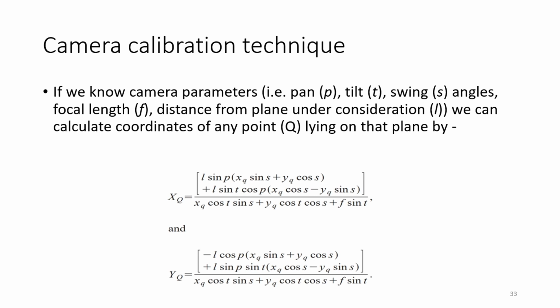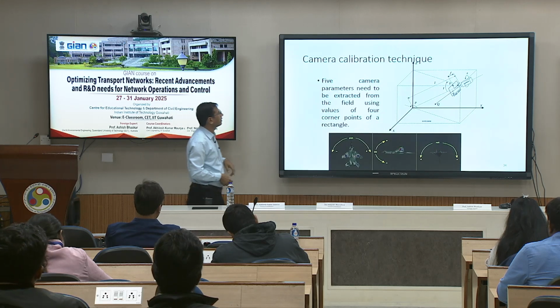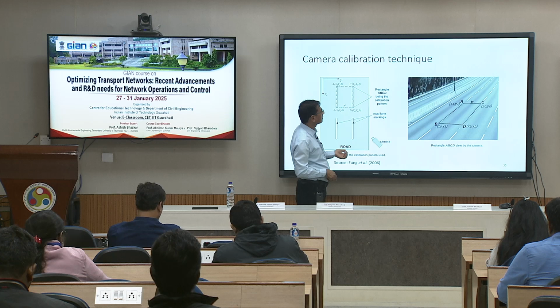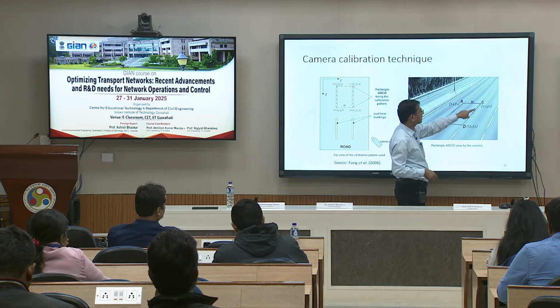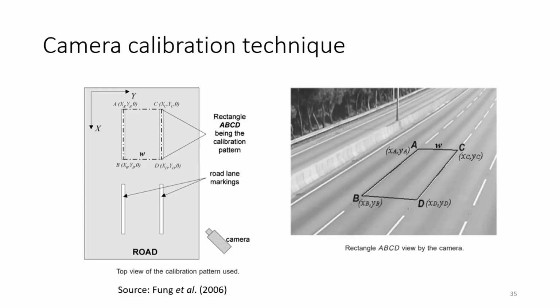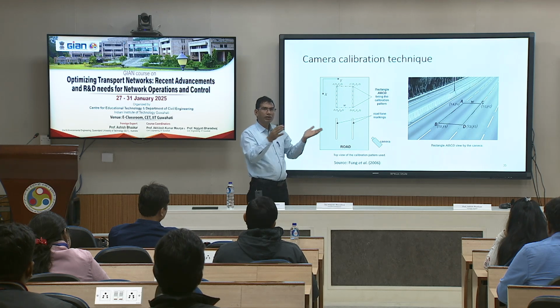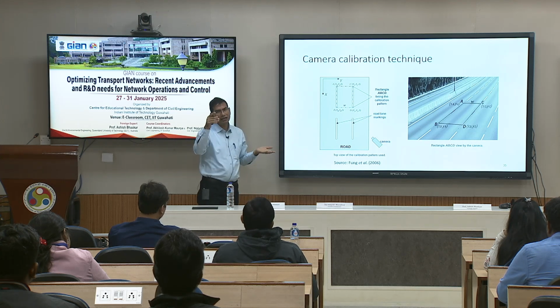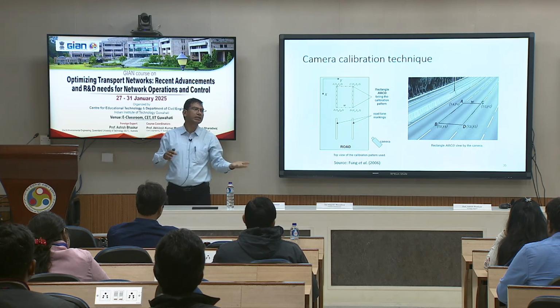These are algorithms which correlate the image coordinates with real-world coordinates. In the real world, you need to have a calibration shape, like a circle or rectangle, whose dimensions are known, and it has to be recorded in the video at the same time. In the image, you need to click on the same points. Then, using a formula, you develop the mapping that shows how the image dimension matches the ground dimension.